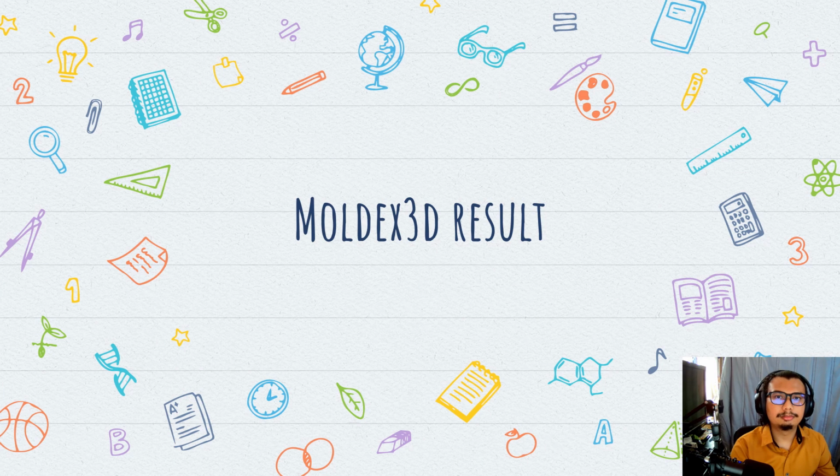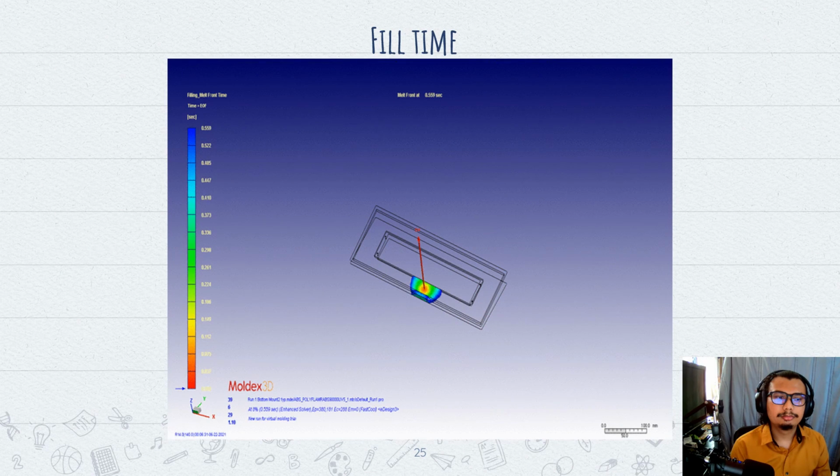Moldex 3D result. As you can see in this slide, this is the Moldex 3D simulation, and we can see the fill time is 6 seconds. And why is the product not filled accordingly? Because this is just a test run. We can see the part is not finished, maybe because the gate system is wrong. That's why the fill time is only 6 seconds.